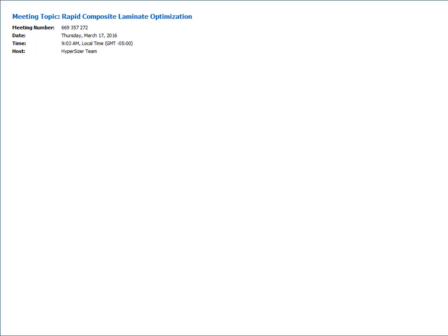One question we had was, I showed a foam example, and the question was, can honeycomb core, your typical Hexcel materials, be used? I didn't show that example, but of course they could be. In an aerospace application, the software is capable, you can put in different densities like 3.1, 4.5, 6.1 PCF type cores. And this is a scenario where you have high out-of-plane shear forces, QX, QY. As it does the optimization, it will tell you what location needs what density core.